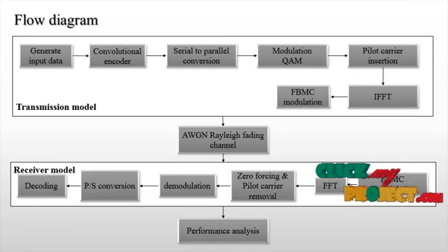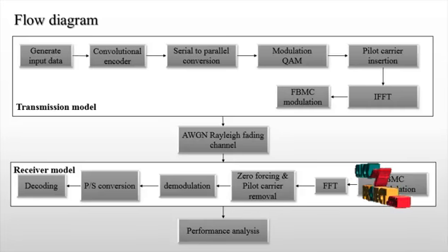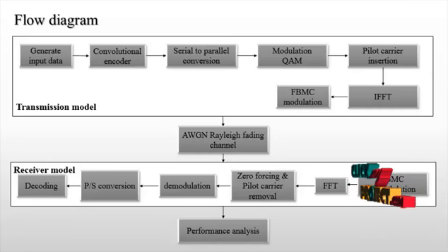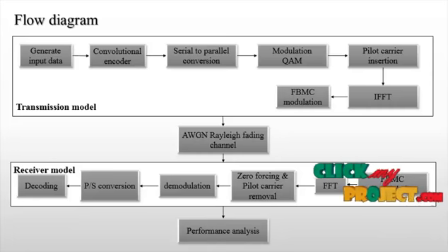One application of a filter bank is a graphic equalizer, which can attenuate the components differently and recombine them into a modified version of the original signal. That is the process of each signal carrying a subband. The process of decomposition performed by the filter bank is called analysis, meaning analysis of the signal in terms of its components in each subband. These are the overall processes of FBMC modulation, and then finally the performance analysis.